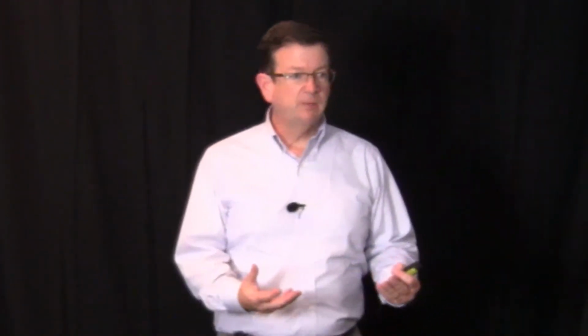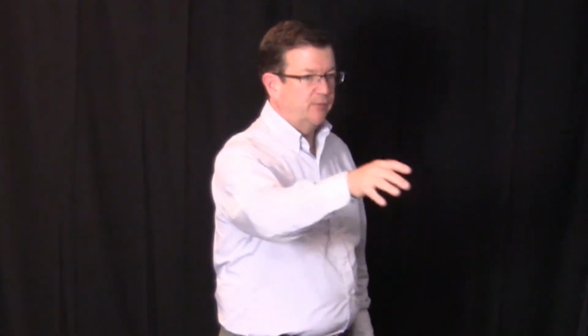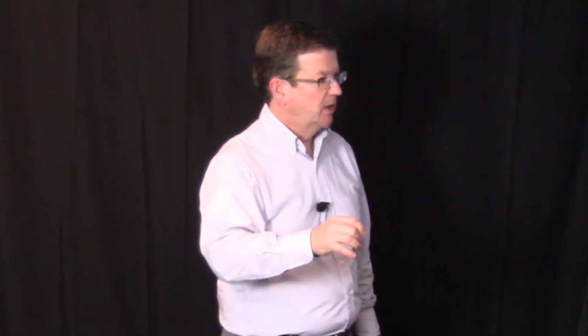The short circuit study is to mathematically model the power system with all the different impedances, the impedance of the utility system, the impedance of transformers, of conductors, to mathematically model all that and to be able to calculate or predict what would be the maximum short circuit current at different locations for equipment. And you compare the calculated short circuit currents with the devices or the equipment's interrupting or withstand rating. That's what a short circuit study is all about.